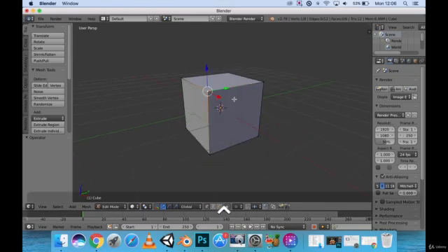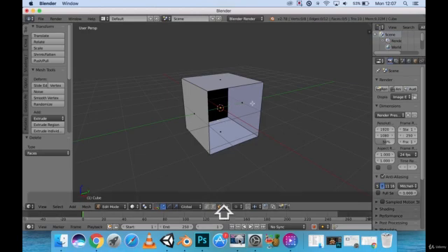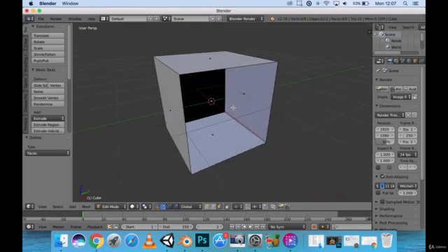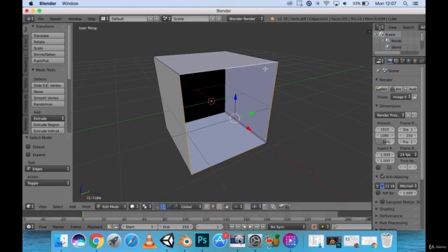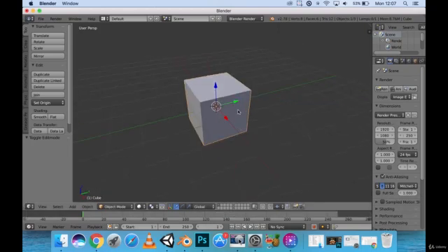Now I'm going to delete one face here and show you how to fill this empty hole in the cube. As you can see, we've deleted a single face. We're going to go into edge mode, simply click Alt, and click one of the edges right here. Now you can individually select each edge here. Just hold Shift, grab one, grab another, and grab this. It's a little slower, right? So it's better if we just click Alt and have it select all the edges in this loop. And if we want to fill in, just simply click F, and we filled in our cube. There you go. It's new again.